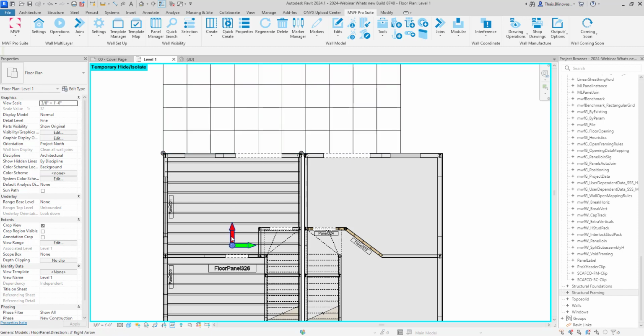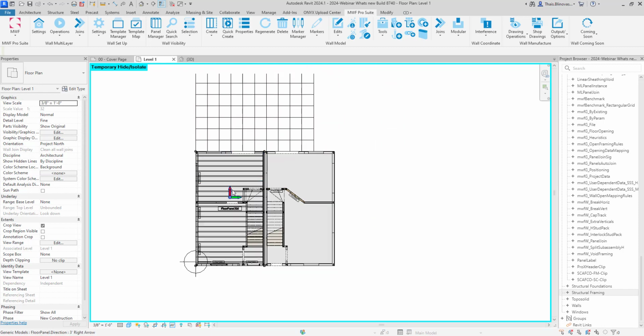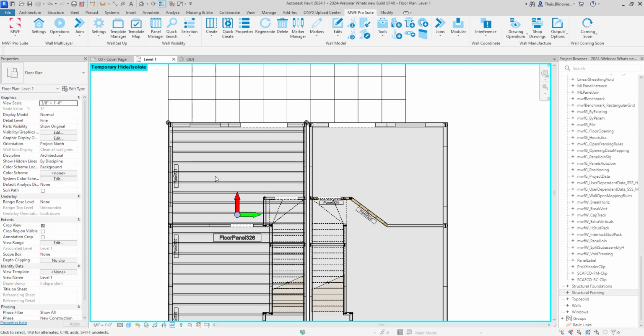If I had that rotated and the joist would be vertical like this, it will be following the width of this grid, which is in that case also 36. So in that case, regardless of the direction of my joists, if I associate them to this grid, it will follow 36 inches in that case because I have 36 and 36 on both sides here.